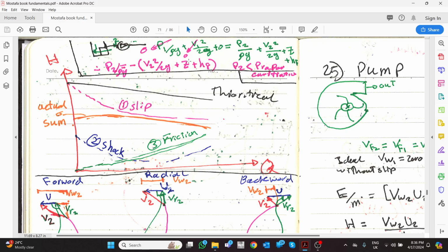This is from the control volume. We already discussed it before. That is, if you have a point, it is about the cavitation. If you need to check the cavitation for the pump, but we're going to discuss it in detail regarding the cavitation and Thoma number, and also the net positive suction head available and required. But a small recap: apply Bernoulli from point to point. Try from the tank. Try here. Put Z here as the datum. Then voila, you will get everything.